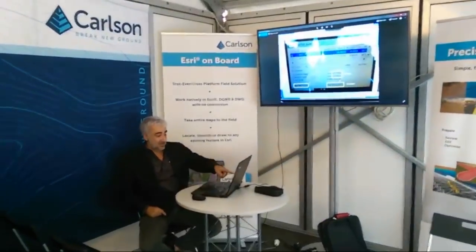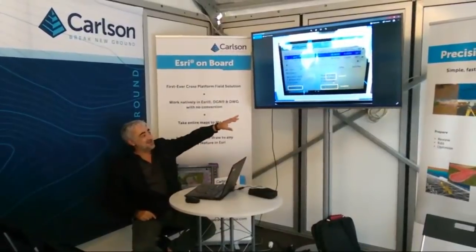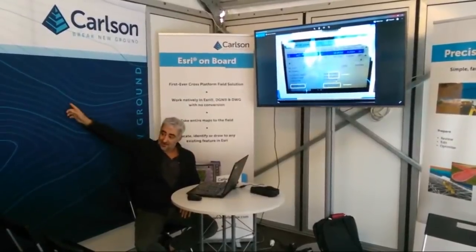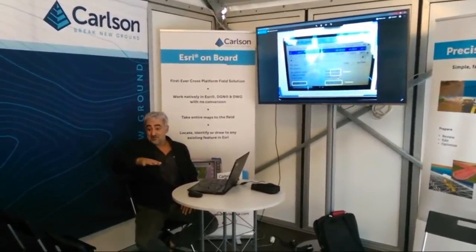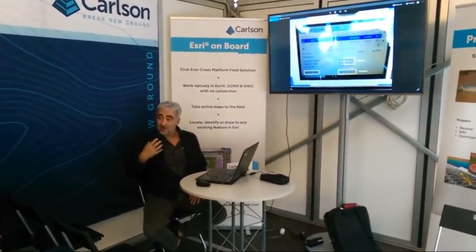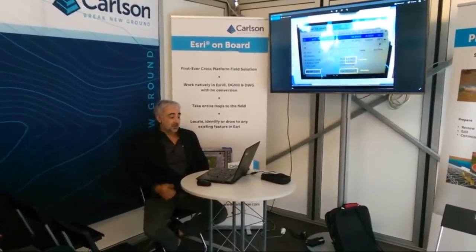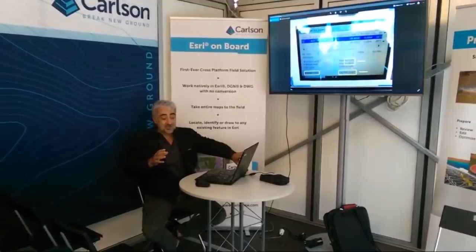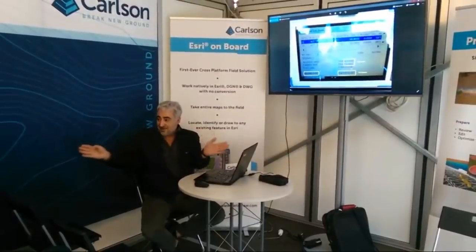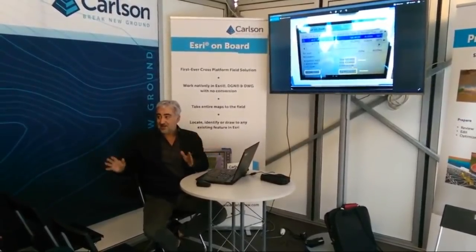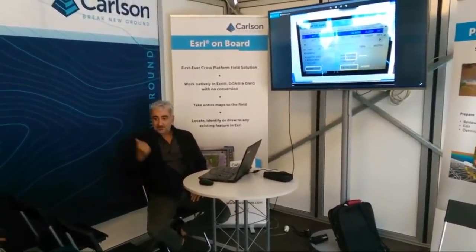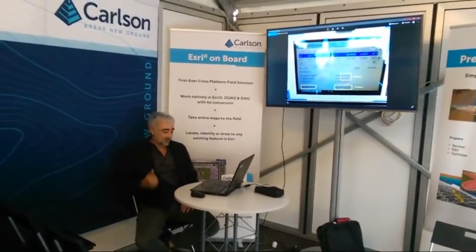Right? So this was done elsewhere, I don't think we can get to this here. I would like to, but we have this building, we have to move close to this building because the other side is the flying area. So we have to move close here. There is a lot of volume here, so the GPS is not even a qualified solution. But we can do our best. And of course, if you want precision, you need to follow the rules of the intersection. So go far enough, open the angles to get good intersections, and you get it. Right? Questions? Or we go up.